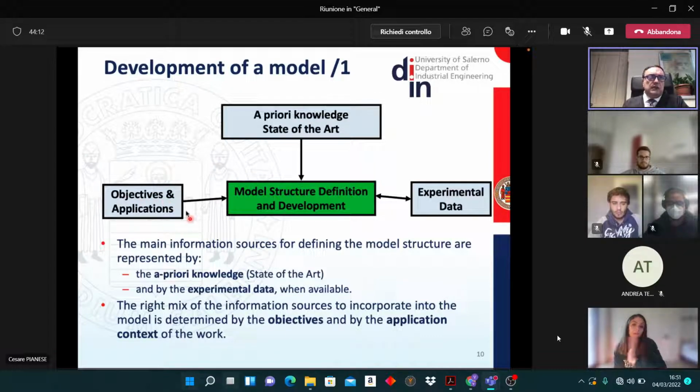The applications are completely different. Perhaps the objectives are the same because your problem is to move these fluids. The applications are different, so you must be careful, because you should be sure that your pump does not generate, for example, air bubbles.